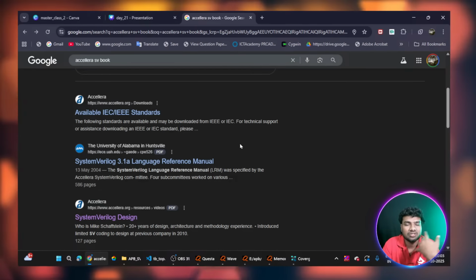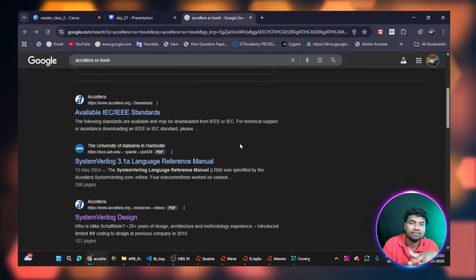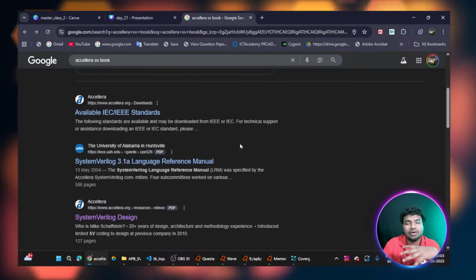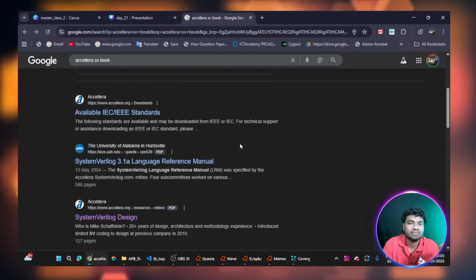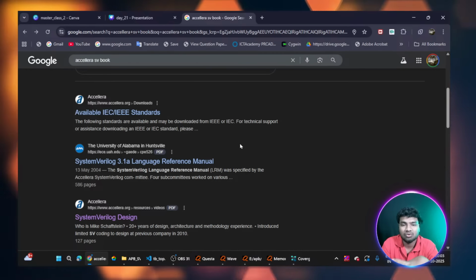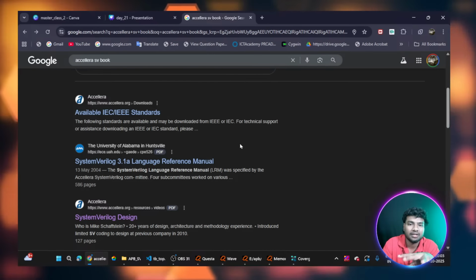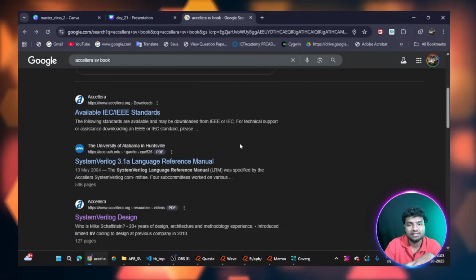So while writing the code, you are writing the master code in Verilog. For the slave address you have to give the correct slave address, and you also have to match the clock frequencies. The LCD module works with a different clock frequency, and your FPGA works with a different clock frequency. Assume your FPGA has 50 megahertz and the I2C has 8 megahertz. So you have to make synchronization between them. That's why I'm telling you, practicing is very good for you.